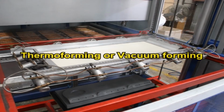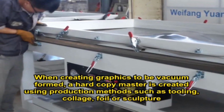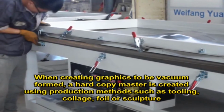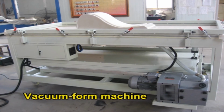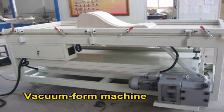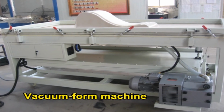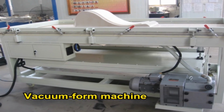Now let us look into the thermoforming or vacuum forming method. When creating graphics to be vacuum formed, a hard copy master is created using production methods such as tooling, collage, foil or sculpture. The heating component and vacuum pump of the vacuum form machine mold a plastic sheet to the shape of the hard copy master. This process forms a plastic duplicate copy while retaining the master for future use.